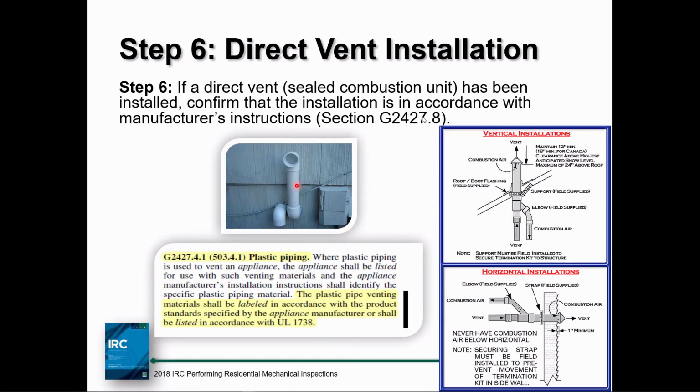One manufacturer has now produced it for the past several years, and I've got to tell you, it's really nice stuff. You could use it with category 4 appliances. So that's how this whole thing came full circle. I like category 4 appliances because the fuel gas part of the code is kind of silent on it for the most part. You're to comply with the manufacturer's installation instructions, the number of fittings, the pipe size, the hangers, things of that nature.